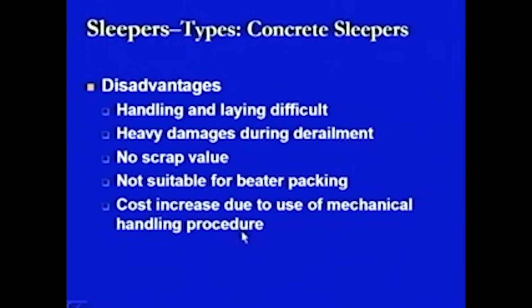The cost increases due to the use of mechanical handling procedures. This is another disadvantage of concrete sleepers. Though mechanical handling is possible, it increases the cost. Because of the heavy weights of these sleepers, we cannot do it manually or using manual labor.